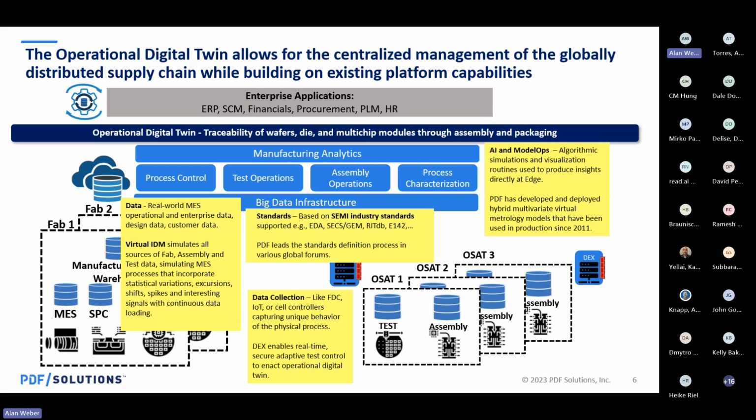These are developed by characterizing good runs and bad runs and knowing where the boundaries are between those things, and then collecting real-time data from the process, putting it through those statistical models and seeing what the results are. The problem with that approach, of course, is that the operating point of the equipment determines which model you have to select. And for a complex piece of equipment, depending on the recipes and the devices and the levels you're running, there may be thousands of actual statistical models that you must choose from a library